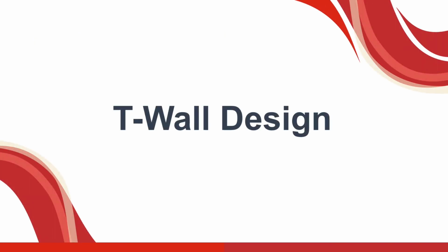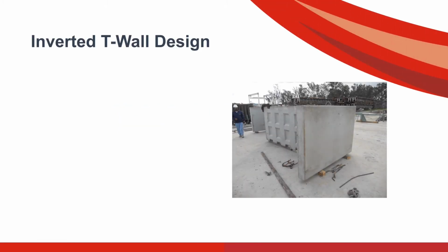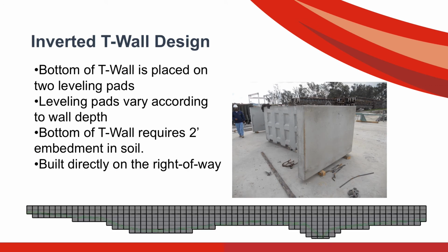The final step in the retaining wall portion of our project was the design. Our CAD specialist, Dane Walker, did the design for the T-wall. The inverted T-wall system is placed on two 15-inch by 6-inch unreinforced concrete leveling pads. These pads lay the foundation for the inverted T-wall system. The leveling pads vary in depth according to the wall depth.